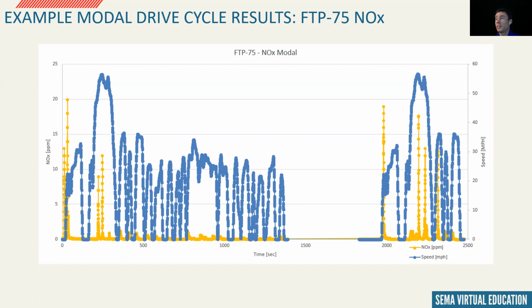Also, if we have excessive boost during transition and transient events, this could cause NOx formation depending on combustion temps and cylinder pressures. For turbocharged vehicles, we might need to calibrate our boost control, PID control in particular, or depending on the strategy, our torque control. If we have lean transitions during tip in and tip outs, we will want to resolve this, as this will create NOx as well.